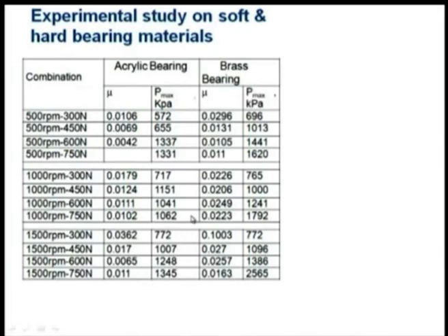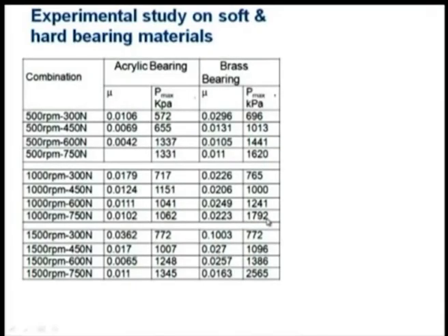Here the surface is also getting deformed. As the surface is getting deformed, it will flatten, and if it is flattening, a reasonable area of the surface will have the maximum pressure. It will not be only a one-point pressure, but a surface pressure. While in this case, we are able to see that pressure has increased to 1.8 megapascal.